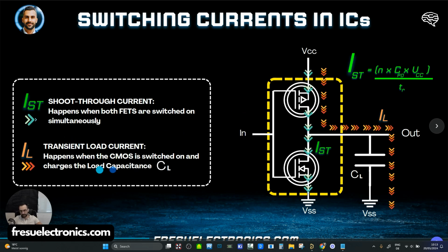So to calculate the transient load current, we are using the load capacitance, and instead to calculate the shoot-through current, we are using this power dissipation capacitance given in the datasheet. Still, we are going to divide it by the transient time of these currents, and this time is typically the rise time and the fall time of the logic gate, which is given in the datasheet anyway.